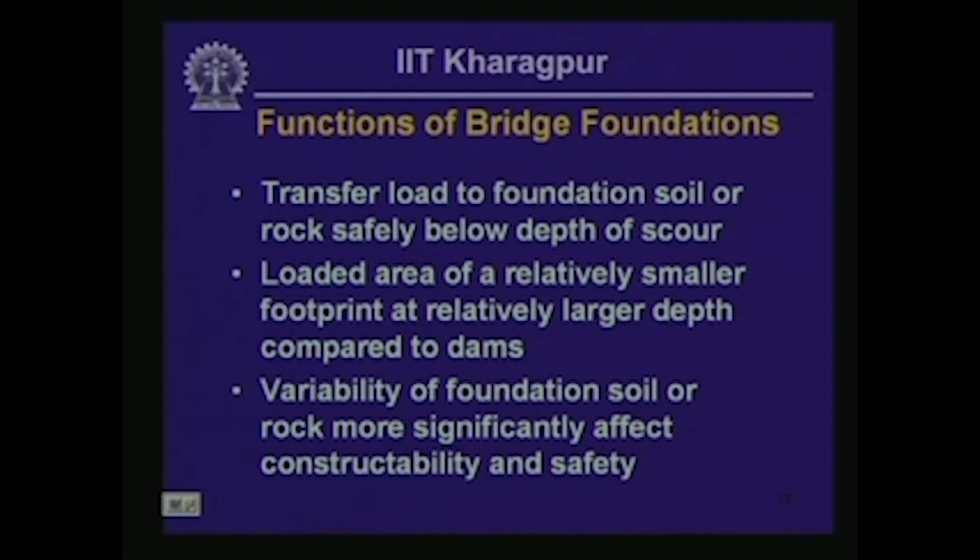So, a very thorough subsurface geotechnical investigation is a must at the location of all the abutments and foundations before bridge construction can be taken up. If the investigation is inadequate or does not go to sufficient depth, the bridge construction would have to encounter inordinate delay because of constructability problems.